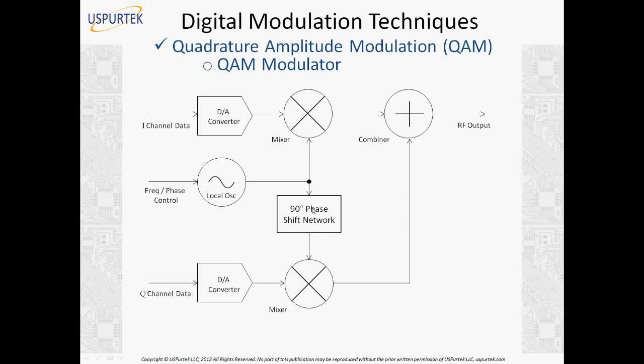Well, there's a question here: are I and Q already 90 degrees phase shifted? Well, they are phase shifted here in the mixer, actually. When you apply the local oscillator, a 90 degree phase shifted signal, that is when you shift, actually. Previously, you just have two streams: an I channel data stream and a Q channel data stream.